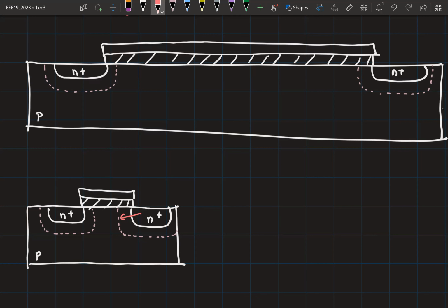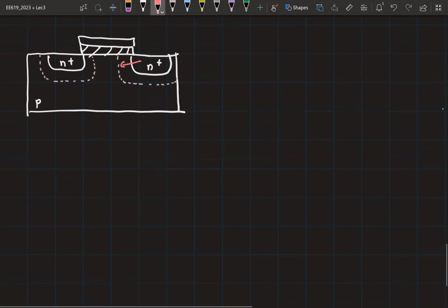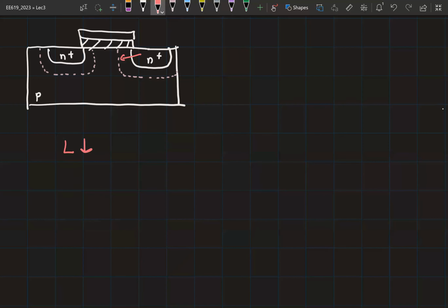As you said, when the distance is small, you would expect the electric field, and hence the drift velocity, to be higher. A small part here is that as you keep reducing your length, you would keep your VDD also small, right? Because if you apply the same level of VDD for small channel lengths, breakdowns can happen. So your VDD also reduces. For example, at 180 nanometer, the typical supply voltage is 1.8 volts. For 130 nanometer, it became 1.2 volts. Now at 65 nanometer, from 1.2 volts, it went down only to 1 volt, right?